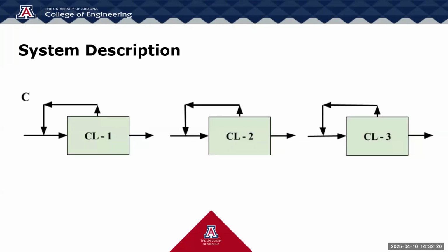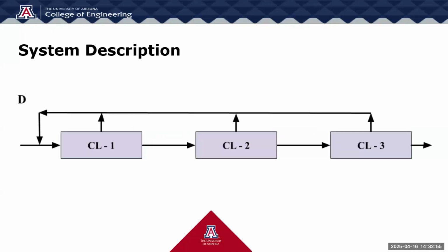Exhibit C introduces air recycling while keeping the cleanrooms independent. The outlet air from each cleanroom is partially recycled and mixed with fresh outside air to help bring the temperature closer to the desired value. With an exhaust to recycle ratio of approximately 0.2, around 83% of the outlet air is reused, significantly reducing the need for conditioning fresh air.